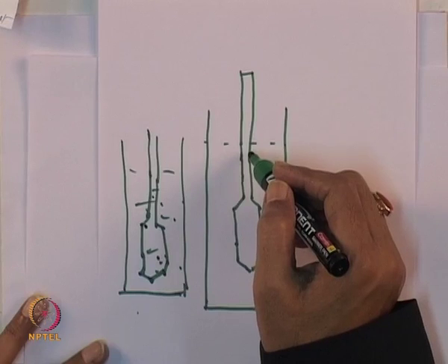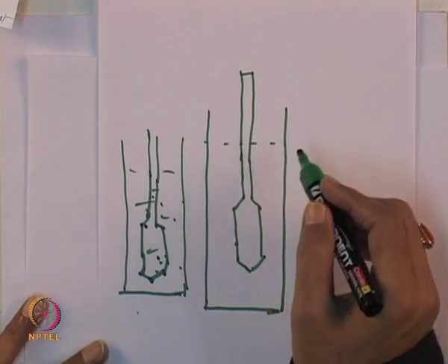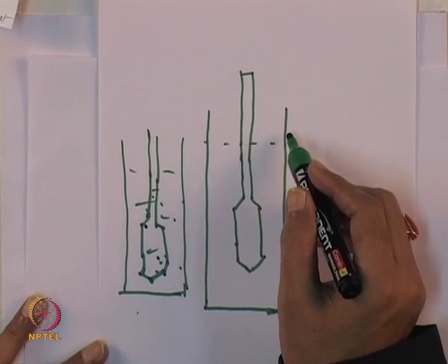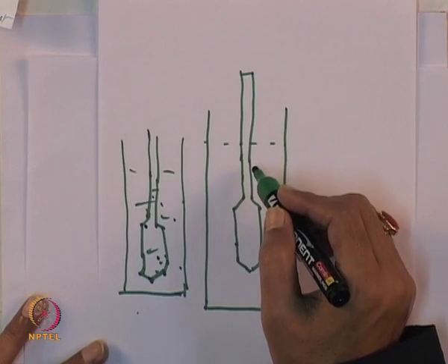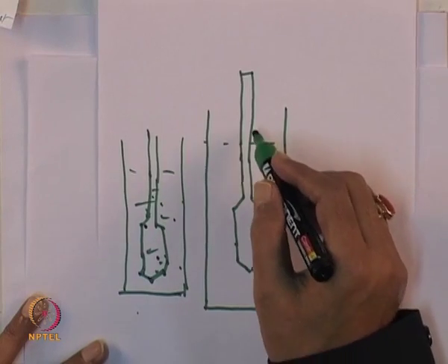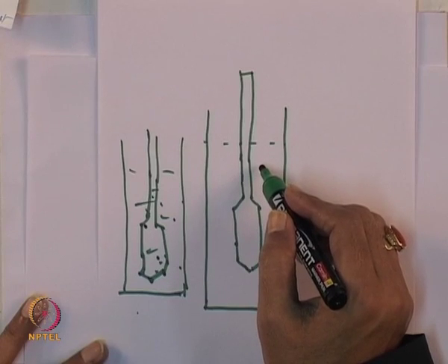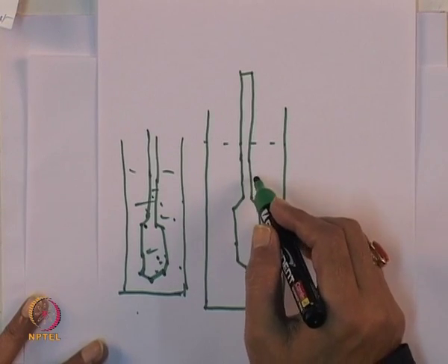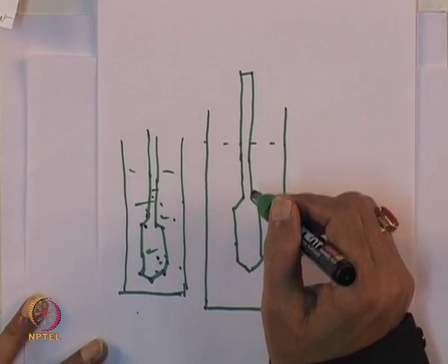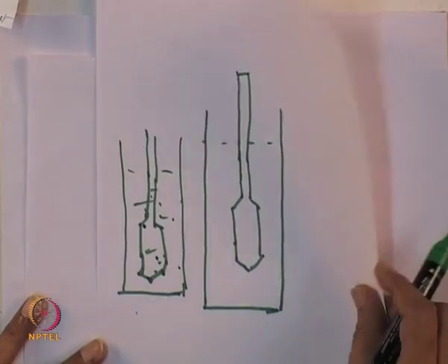Take the subsequent readings after 5, 10, 15, 30, 60 and 120 minutes, and record the temperature of the soil water suspension using the thermometer, and leave the suspension as such for readings to be taken after 24 hours and 48 hours.